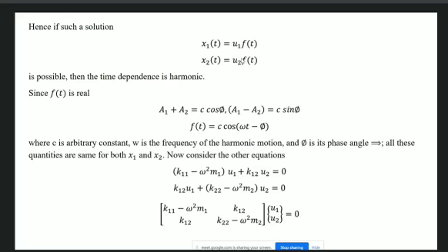all of you know, in any general situation of the vibration, all the modes participate in general, but the extent of the participation becomes different, and always the maximum participation becomes that of the first mode, and then the second mode, then third mode, and so on. Because to excite the participation in the first mode, the energy required becomes least. And as I have told you, most of the phenomena of the mechanics in this universe can be explained in terms of the energy principle.